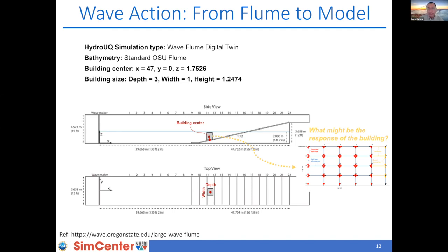I would perhaps emphasize that this simulation is actually done without any coupling between the structure and the fluid responses. It's more like a post-processing stage for CFD, and it generates the external loads for the building to do the separate analysis in the second stage.